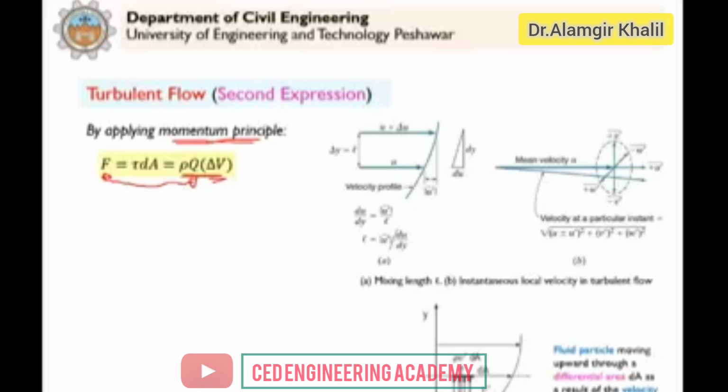In this figure, you can see that in case of turbulent flow, the velocity has fluctuations. Let's say this represents time. With respect to time, if I plot the velocity in the x direction, that is represented by u. One is the average velocity, represented by a straight line, and we write it as u with a bar.